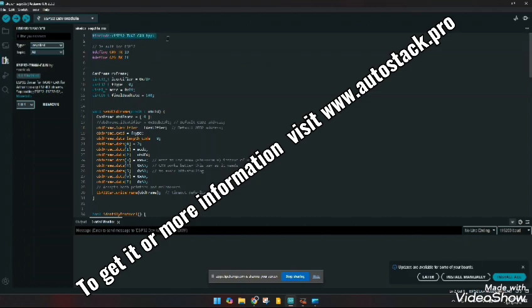First, we have included our library and defined the TX and RX pins of ESP32, which are D19 and 21 in this case. And these two pins need to connect to the CAN transceiver, and the CAN transceiver will be connected to the OBD port.